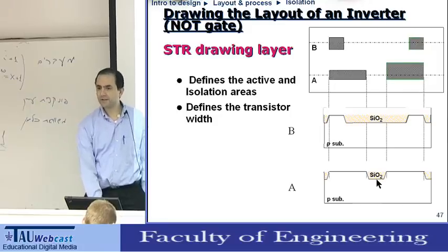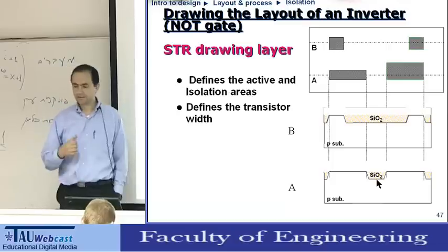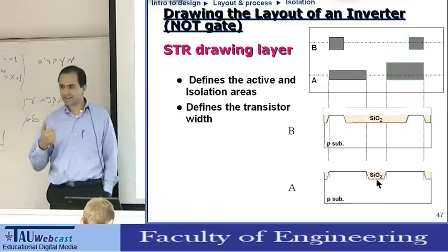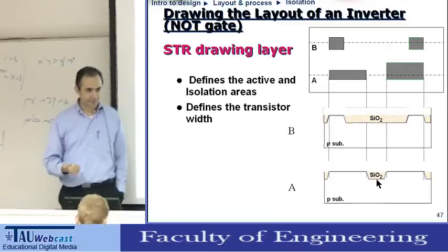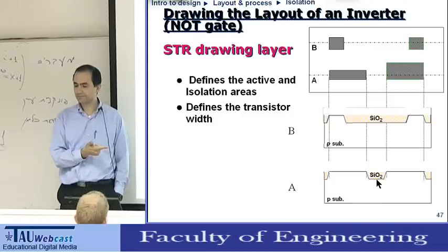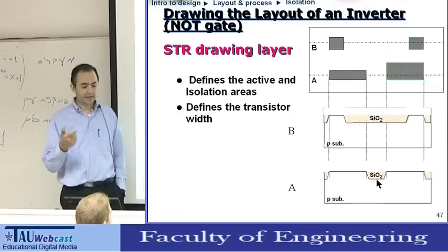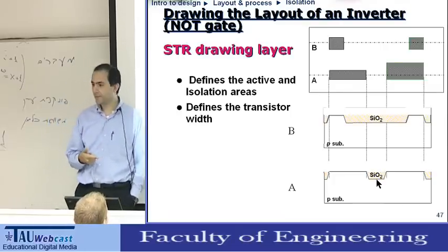How do we etch the silicon? Dry etch. What would be the first step? Breakthrough etch, right? And then the next step will be fast etch. It will be some kind of silicon etch. And how will we know when to stop?